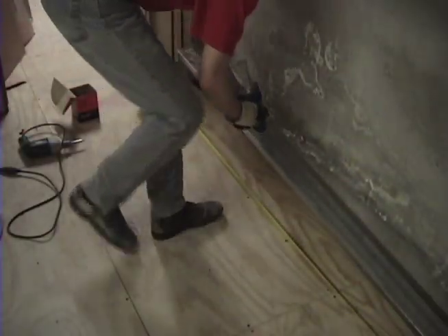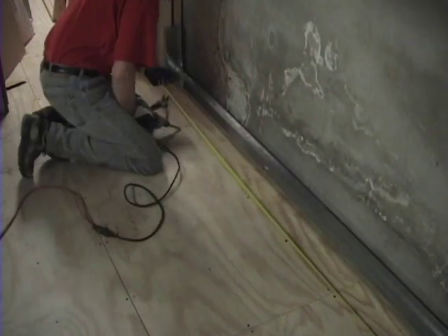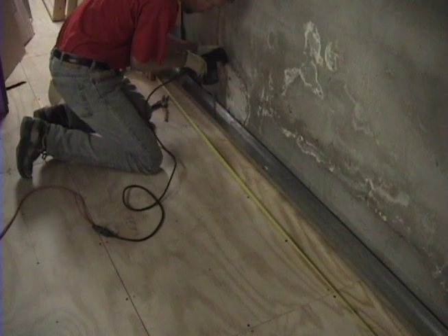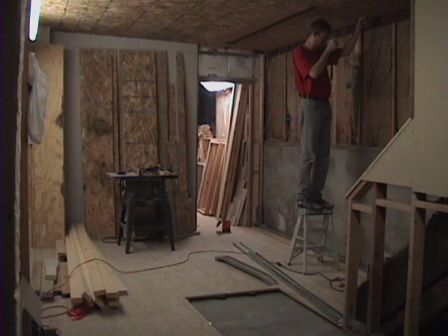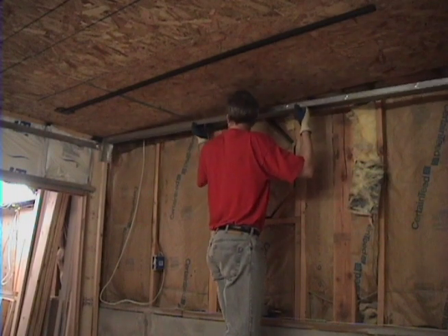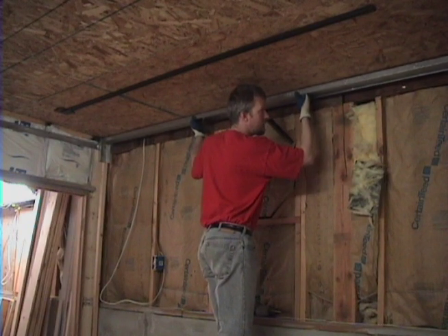After the cuts have been made, you can put a bead of construction glue on it to hold it in place. Then use small drywall screws to go through the steel and into the subfloor, but not into the floor of the structure. The top plate can be installed in the same fashion as wood, by using a plumb bob to find the corners and to make a chalk line. Steel studs are completely straight, so there's really no need for a chalk line here, but I find it helps to clarify that everything is in the right place.